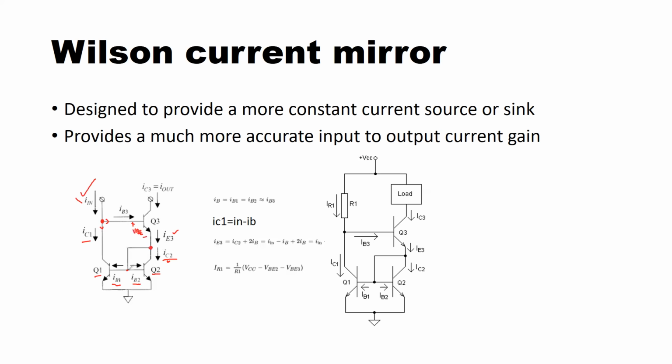Then the voltage at the base of transistors Q1 and Q2 starts to rise, which gives rise to base currents, and therefore collector current starts to be drawn. So there is a current flow through the collector of the transistor.